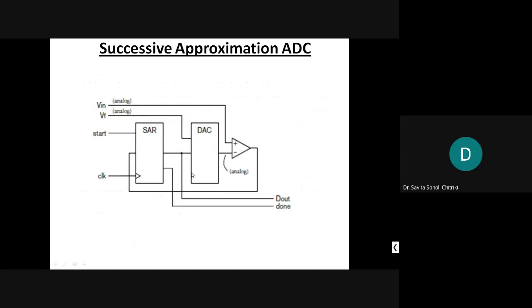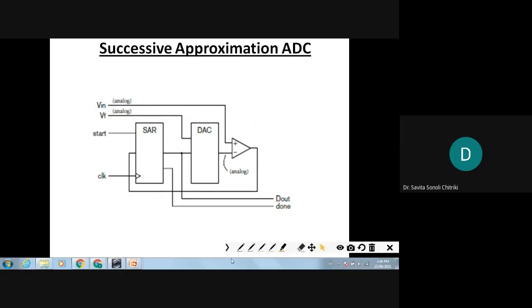So this you can see. Here either 1 or 0, whatever is generated as the output, goes on to the successive approximation here. So that is appended as an MSB bit. That output bit is updated as the MSB bit. The remaining bits are all shifted one position.